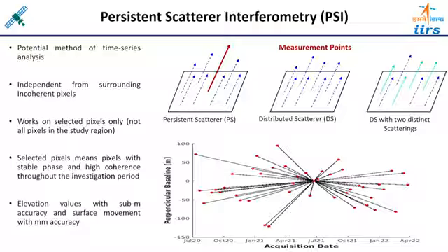So that is only possible if you are taking the reference almost in the middle, but you cannot choose the middle arbitrarily; you have to do the calculation according to the relationship which I have shown in the first slide. If you do that analysis using that relationship, then automatically you will get the reference image almost in the middle. This way we are forming the interferograms and then generating the time series of the phases between the reference and the secondary images, and those phases are converted into deformations. So the time series of the deformation can be achieved.